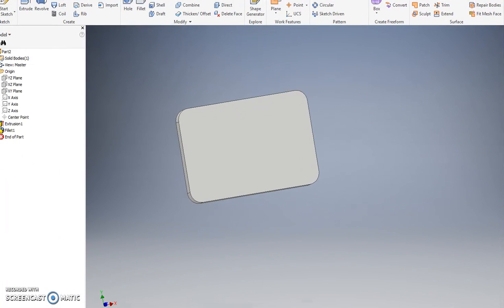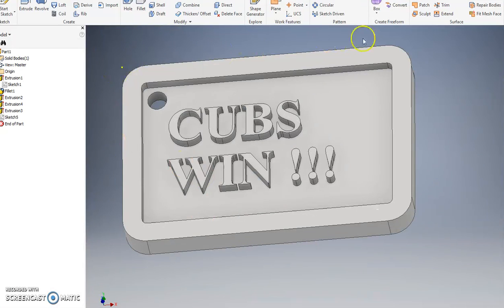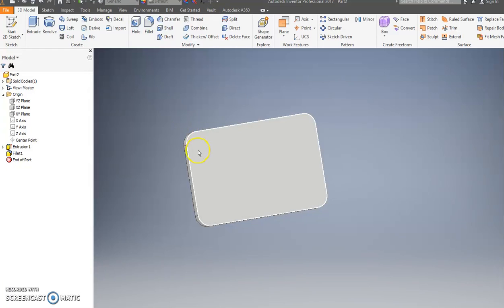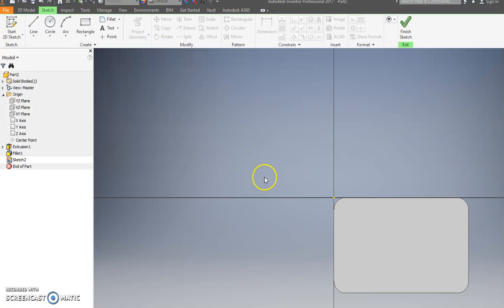So, as you can see from the first part I made, we got the round part done, or the outside part done. Okay, now in Inventor you can make what's called a sketch on almost any plane possible. So I'm going to click the top of this. I just left clicked. And you click this guy right here. It's called Create Sketch. Okay.